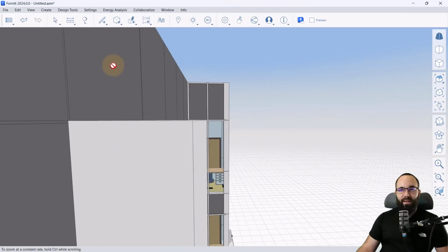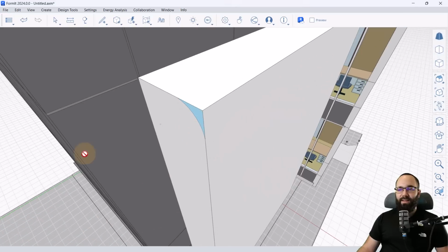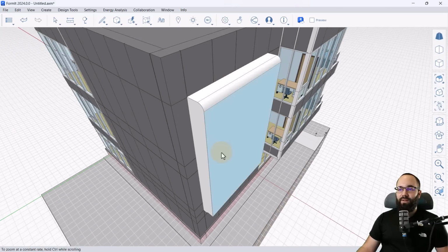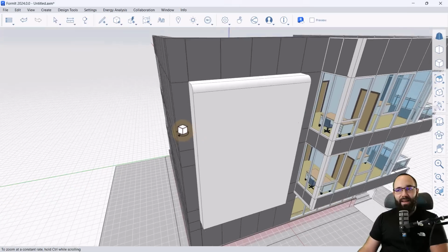So for that, I'm just going to go here, find an arc, and then let's go from here at a 45-degree angle, just like that, then create an arc just like this. Switch back to a line, and then let's just create a shape like so. Hit the escape key a few times, select this, and then I can just push it away, and it's going to create a clean cut at that edge.